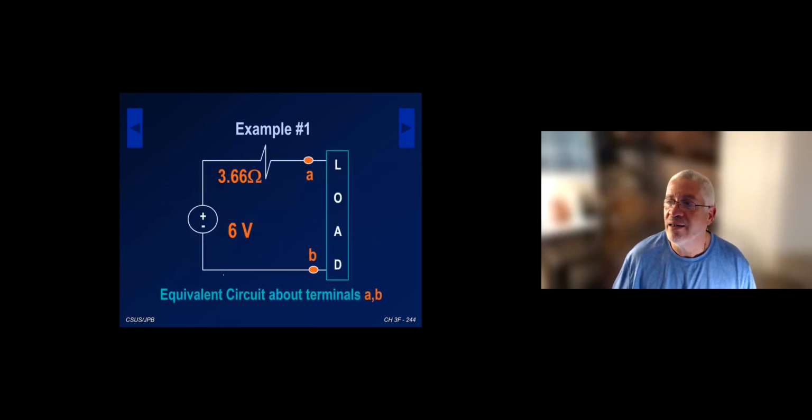And finally, this is your Thevenin model, which is an exact model, by the way. The Thevenin model is VOC being 6 volt in series with the Thevenin resistance being 3.66. I hope this gives you a pretty good introduction of what the Thevenin model is. I want to do a second problem just to give you a little bit of a different feel for the solution. But this actually provides you the essence of the Thevenin model for circuits.